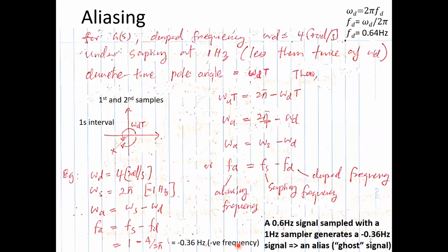Remember, just before the break, we discussed observer-based control. There, the observer improves the bandwidth. So you originally decide a certain bandwidth, and now it's a little more than that. You allow higher frequencies to come in, and there's a sampler which takes the samples properly before the observer. Now with the observer, it fails, because it generates aliases. The sampling is now not fast enough, not twice as fast as the bandwidth frequency, because the bandwidth has been increased with the observer-based design. See, this is how things interact with each other in the control design process.